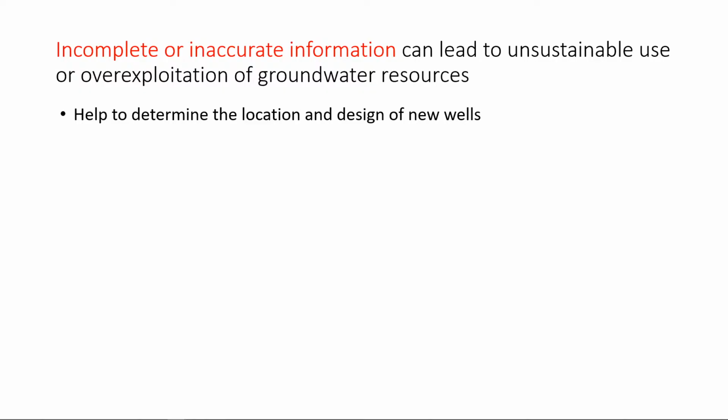When you do an aquifer test, like a pumping test or a slug test or any test, this will help you to determine the location of the new well that you want to drill, whether it is a pumping well or a monitoring well.